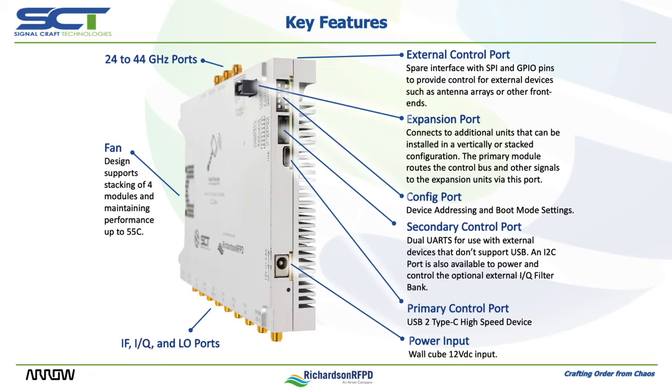Two APIs are available. The first is ASCII-based, and its commands follow the SCPI structure as defined in IEEE 488.2. The second is a binary protocol, targeted at embedded control applications where speed and timing may be of concern. Both protocols are defined in our API specification, which has been posted on the support portal.